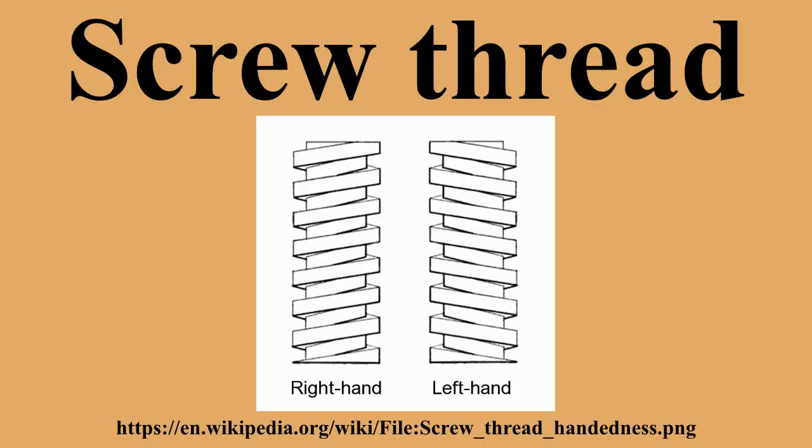Metric uses DA/DO limits, which is the same system as imperial, but uses DA/DO designators for over and undersized respectively, and goes by units of 0.013 millimeters. Generally, taps come in the range of H1 to H5 and rarely L1. Standardization and interchangeability. To achieve a predictably successful mating of male and female threads and assured interchangeability between males and between females, standards for form, size, and finish must exist and be followed. Standardization of threads is discussed below.